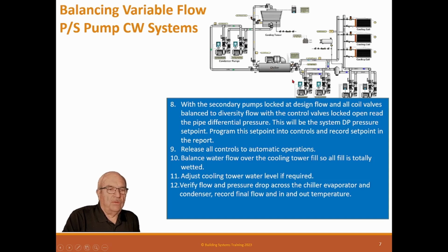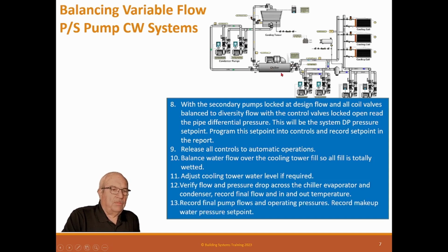Verify flow and pressure drop across the chiller, evaporator, condenser. Record final flow and in and out temperature. Another thing, record final pump flows and operating pressure. Record makeup pressure set point, what the set point for this makeup water is.